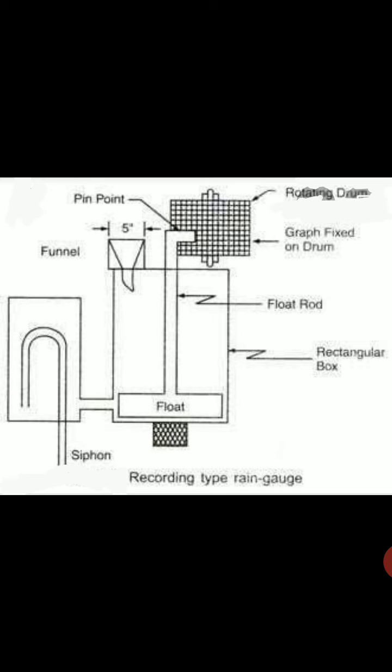Errors in rain gauge measurement and estimating true rain catch. The first error is mistakes in reading the scale of the gauge. Second is some amount of water will be displaced by the measuring stick, or water may creep up the stick. This may increase the error by 1%.